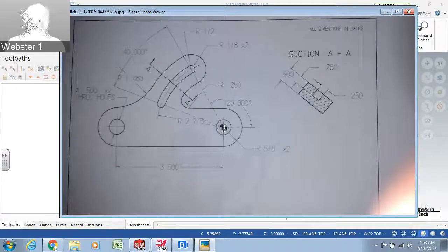So we could put the origin here, and there's a lot of information coming off of that. So in this case, why don't we go ahead and draw this as the origin. I would start by creating this first circle and maybe another circle around that, and then drawing these other two circles, and just start getting the part geometry on the screen to size.